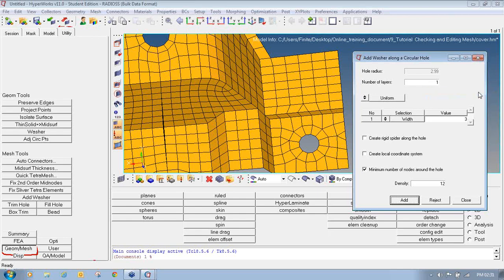So in this way you can edit the existing mesh data and improve the quality of your elements. The better the improvement, the better will be the results of analysis. In this tutorial, we have seen how to identify the shell elements connectivity problem, how to correct the shell elements connectivity problem, and how to review the model shell elements to ensure connectivity problems were corrected.